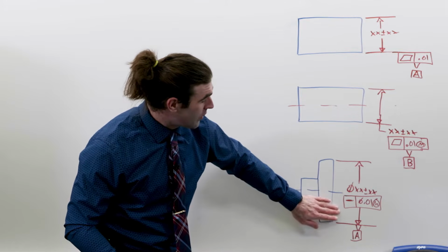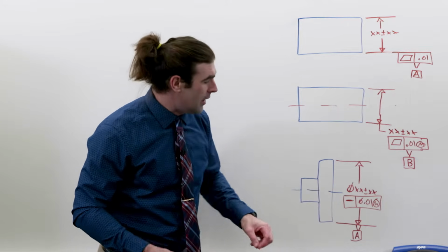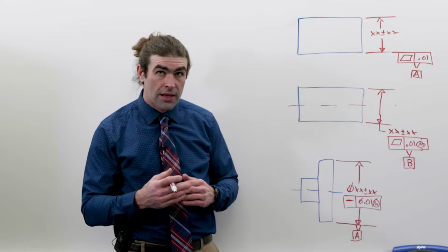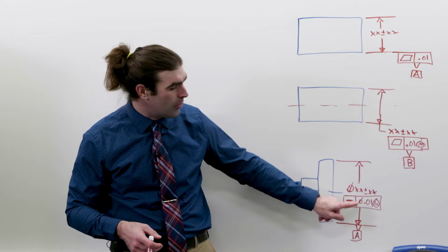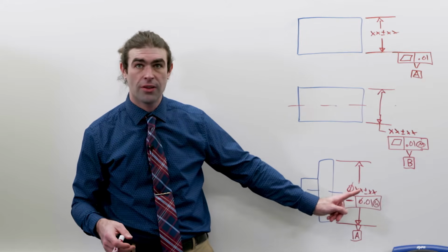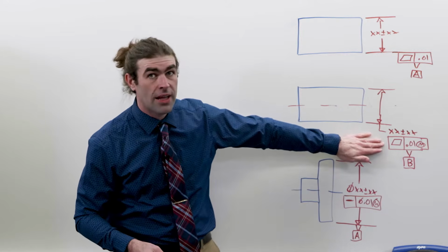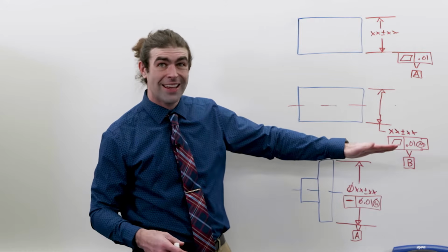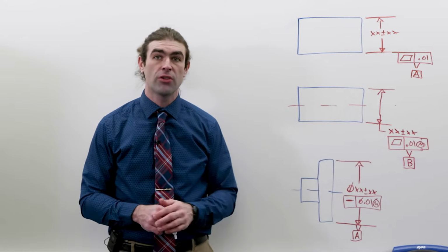With a cylindrical feature, we've got a feature control frame. Normally, right here, you wouldn't put the datum feature symbol on the feature control frame because it'd get in the way of the dimension line. So you would do what I did right here, move the dimension totally out of the way and then put the feature control frame on it.